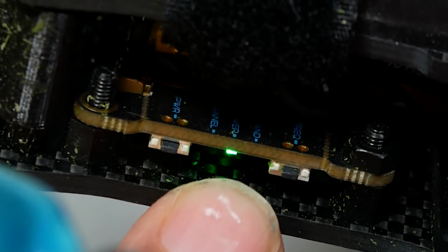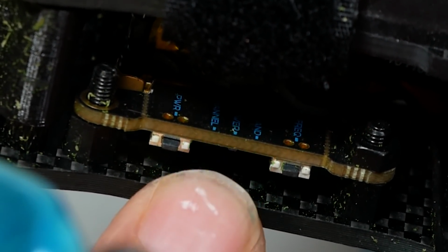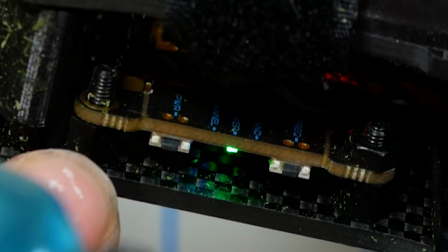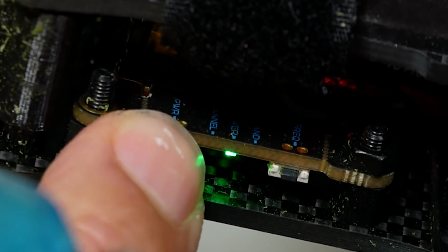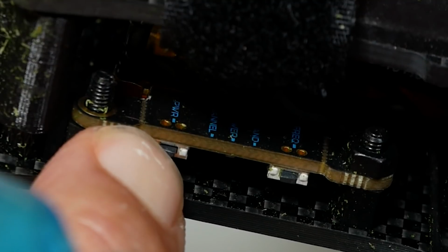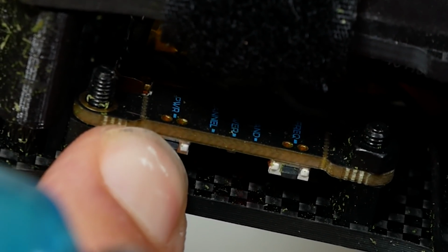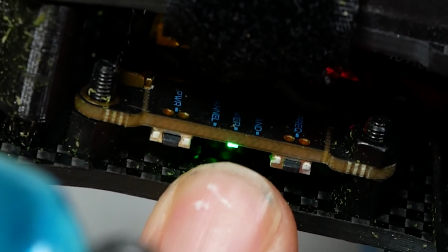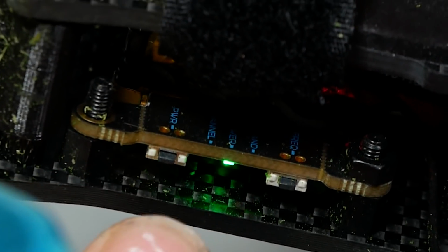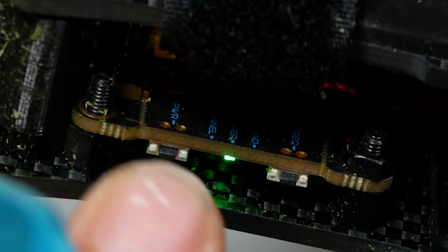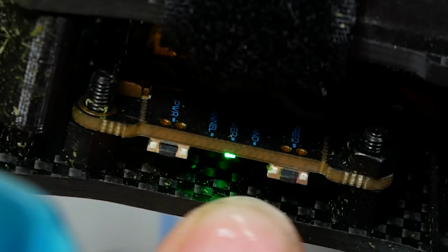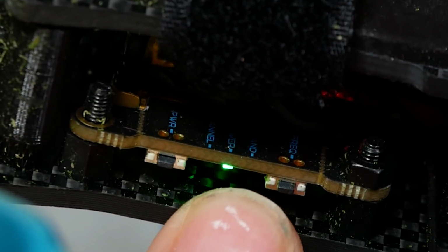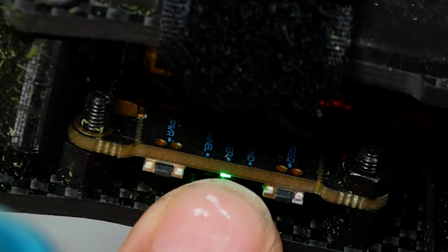And so if you have terrible range and terrible video, take a look here. And if your LED is blinking, like you see mine blinking here, the way to take the VTX out of pit mode is to long press the power button. And when you do that, when it comes back, it will be solid. Now you should also be able to take the VTX out of pit mode using the SmartAudio menu that I just showed you how to set up. But if that seems to not work or you have any trouble, take a look at this and long press that button to make sure you have a solid LED like you see here and not a blinking LED.